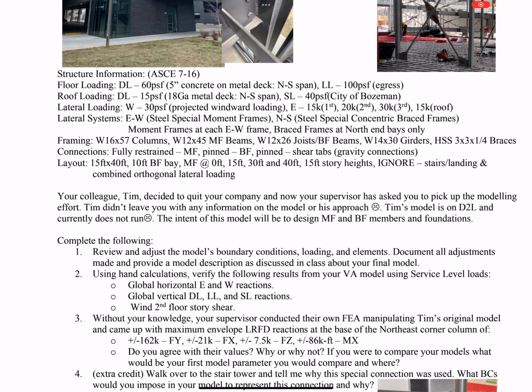The other one is seismic, right? If you have a brace frame and a moment frame that share a column, right, in two orthogonal directions, you technically, based on the code, need to give it 100% in one direction, 30% in the other direction, right? Don't worry about that, okay? Don't worry about the combined, just look at this loading in the two directions, okay?